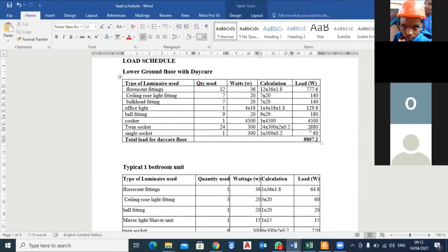And then with a diversity factor of around 0.5, it will come to around 3,000. So 10 is an ideal number because it will not go beyond 3840. It will not go beyond 20 amperes that a cable can carry.